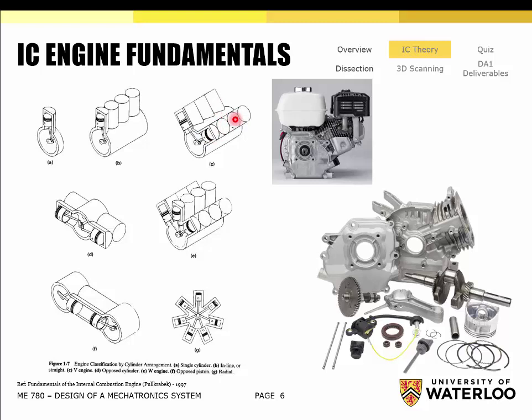What about the middle cylinders here? Okay, they only have 50% of their surface area exposed to the free air. However, this radial configuration has a higher percentage of all the cylinders having exposure to the free air. So if you were to redesign the cooling fins on that, you might say, okay, I want to make them really large, but maybe I want to make sure that air can get to every part of the actual cooling fin. Because if there's something stuck against it that the air doesn't allow it to travel to, it's causing issues with thermal efficiency. Yes? That means that it's limited for the air engines in the propellers?